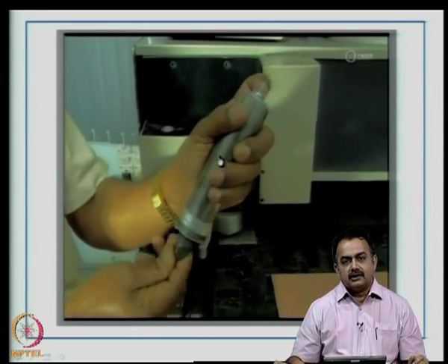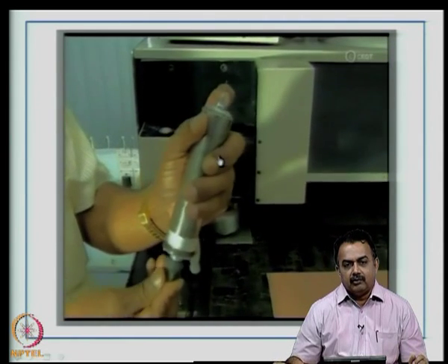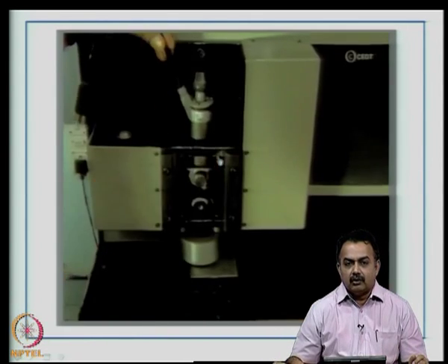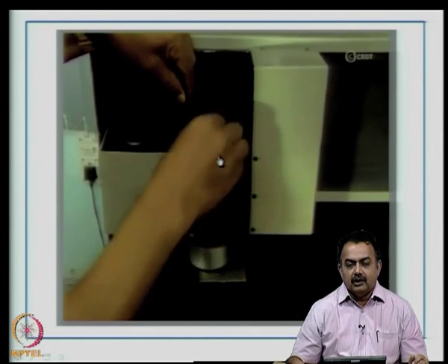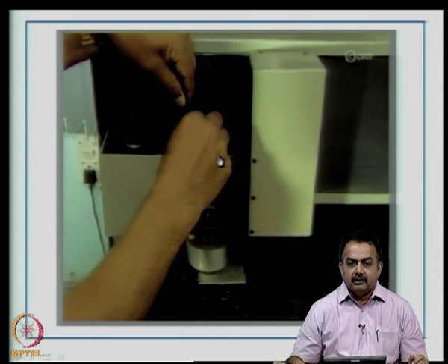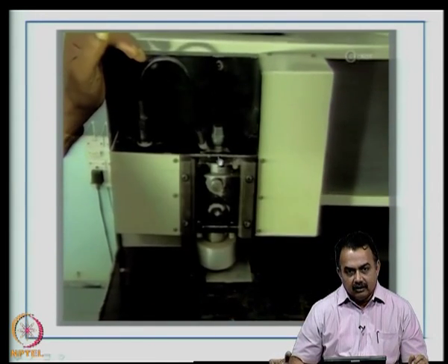In some cases, typically after let us say a multi-layer board is finished, you want to do controlled depth drilling. In that case, you have to readjust the drill bit to the required depth that you want, because in those cases you do not want through and through drilling to be done.